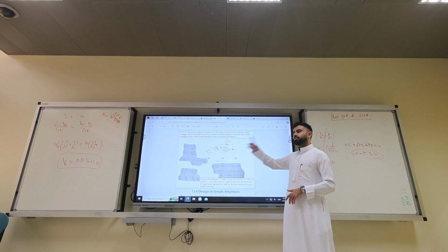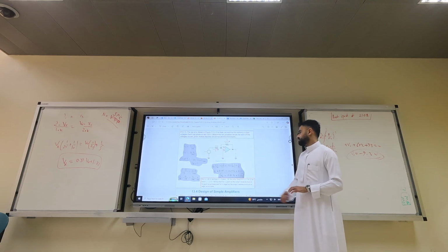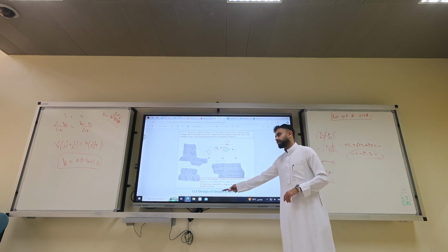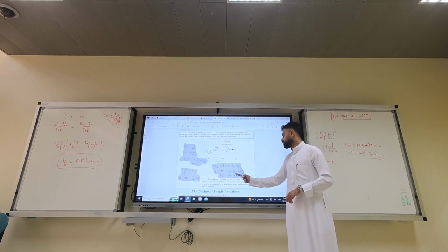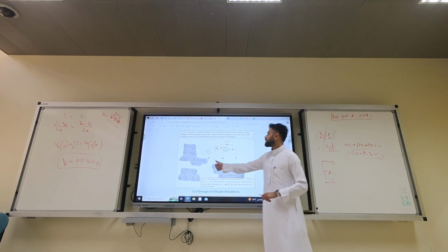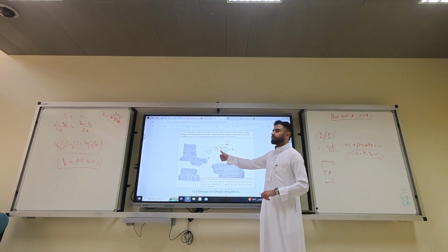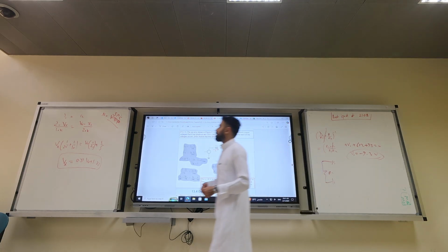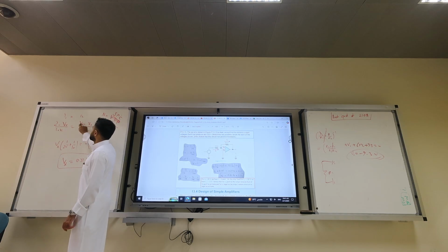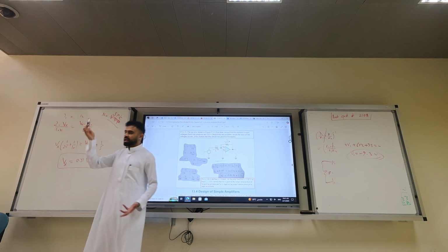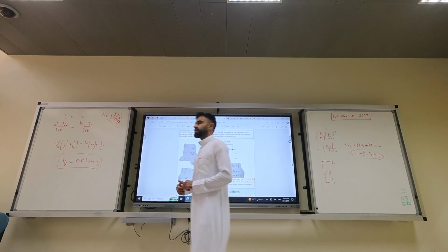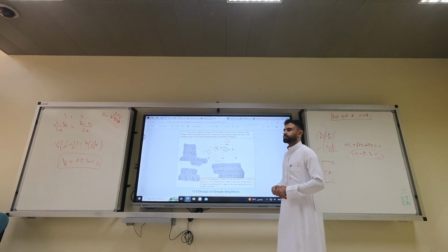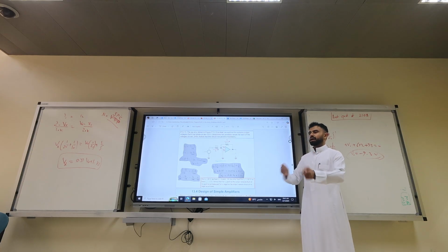And if it gets to 10, it will remain stuck. Notice that for Vx positive, the output remains stuck at its positive extreme. For Vx negative, the output remains stuck at the negative extreme. So we don't know. If you provide a positive input here, it will be either 10 or minus 10. We don't know, because here you have an equation of 2 variables. Whoever catches first would impact the other. It's an unstable situation. It has to do with what goes inside the chip, which transistors will ignite first.